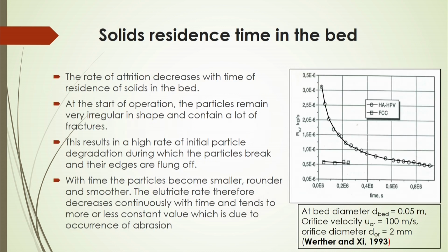Another important factor is the solids residence time in the bed. How long will these solids reside inside the bed? If the contact time for collisions, or the residence time of the solids, is longer, then more attrition can be expected. So, the rate of attrition decreases with the residence time of solids in the bed, if they are not residing there for a longer time.